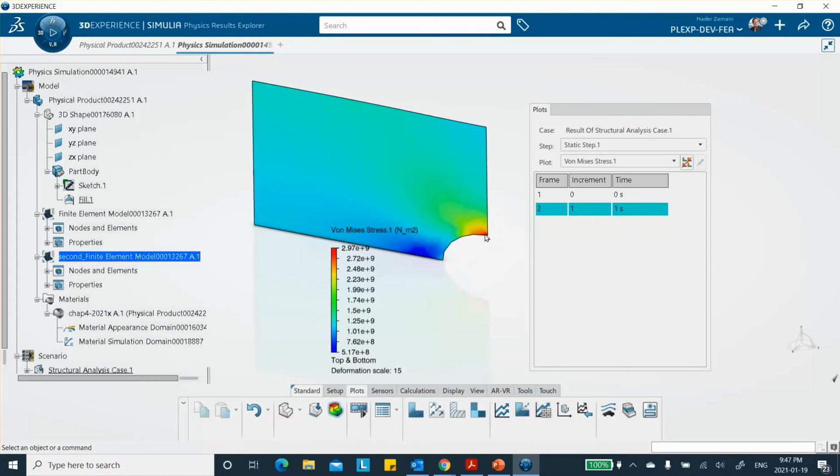However, I also show you in the book how you do a local mesh refinement along that edge. You can check it out. But if you're going to do local mesh refinement, it should be in this area, not back there. Nothing fancy, nothing exotic is happening back there. But over here, there's a big change in stress, and you want to refine it in this area.